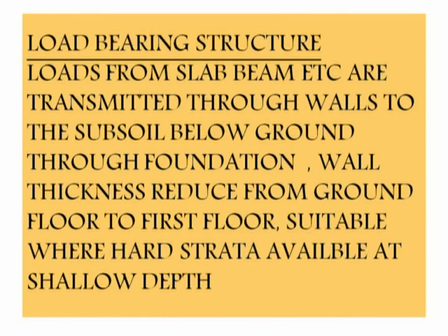Wall is a very important component in the case of the load-bearing structure. Now, as you know that the load from the top to the bottom will increase, the wall thickness reduces from ground floor to the first floor. Because as you go on the top, the load will be reducing, and therefore as the load is getting reduced, the thickness of the wall is a little bit reduced.